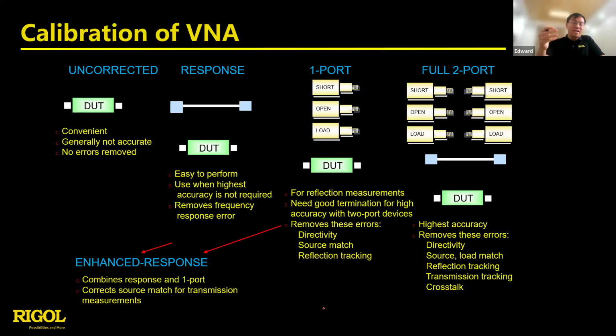Yeah, so you can see how important the calibration procedure is compared to the test procedure by the network analyzer. The calibration procedures can include the open, short, load calibration kit, or if you have a 4-port, you need to go through the open, short, load calibration for every port, and through if you want to do the loss measurement or the DTF, TDR measurement.